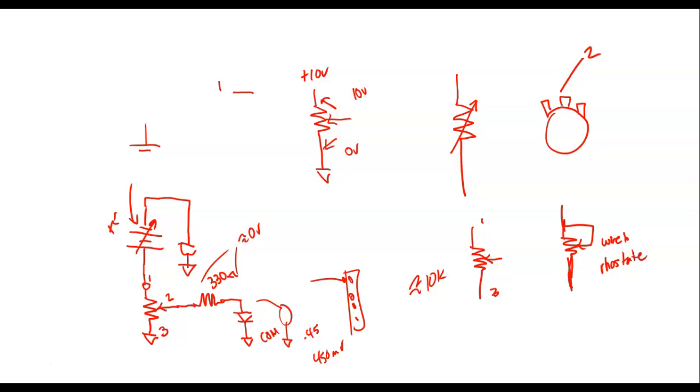And we're going to get our current, not by measuring current. We're going to calculate our current through our diode, not through the pot. We're going to use the pot to set the voltage. How are we going to calculate our current? We're going to measure the voltage drop.